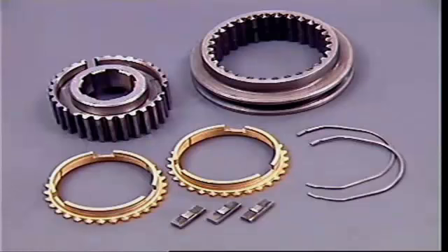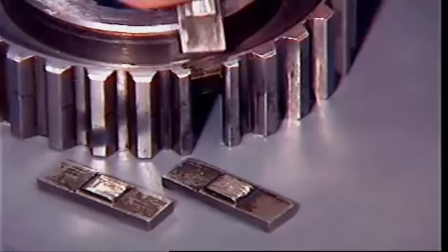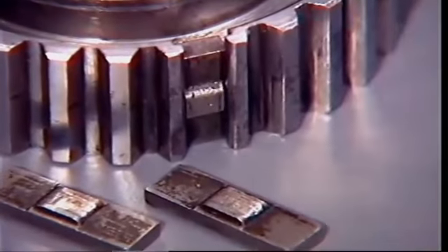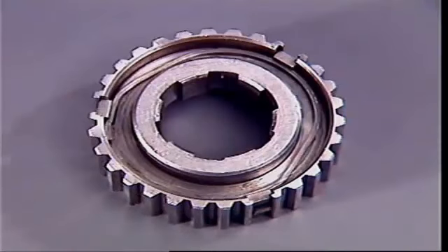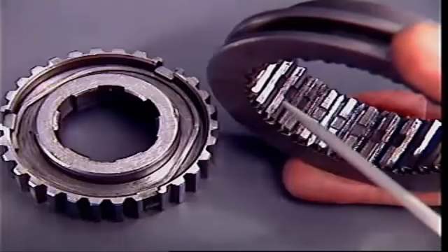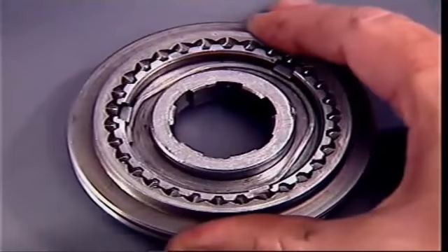A Borg ring type of synchromesh unit is commonly used to synchronize the speeds of 2 gears before engagement. 3 metal inserts with a ridge fit into slots in the hub. A radial spring at each end holds them out so that the ridges locate in a groove inside the sleeve and hold it centrally on the hub.